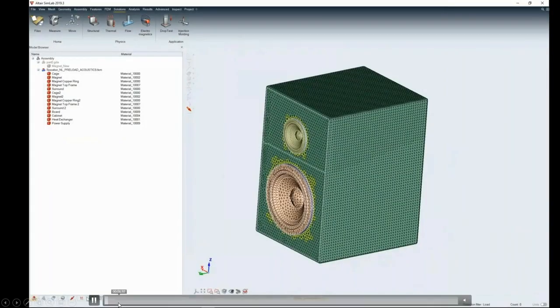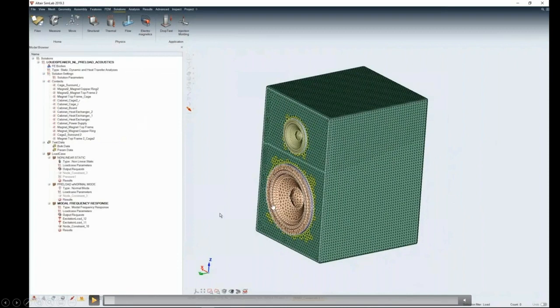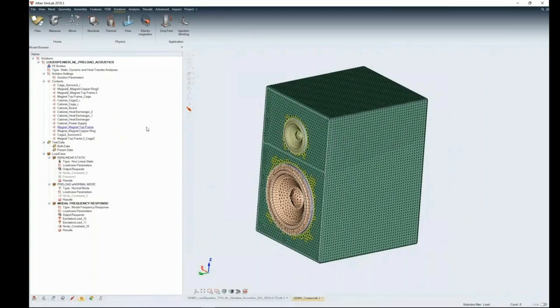While looking at the contact definition here, I would also want to bring to your attention where we saw the model browser. Now here is the solution browser. In the tabs at the bottom, you can drag onto and look at the solution browser where all the solutions are set based on the type of analysis you're doing. And on the top in the solutions, you can pick between different solutions. Now, I will go into a little more detail of that in the next set of demos, but here, let's look at how these contacts are taken care of.